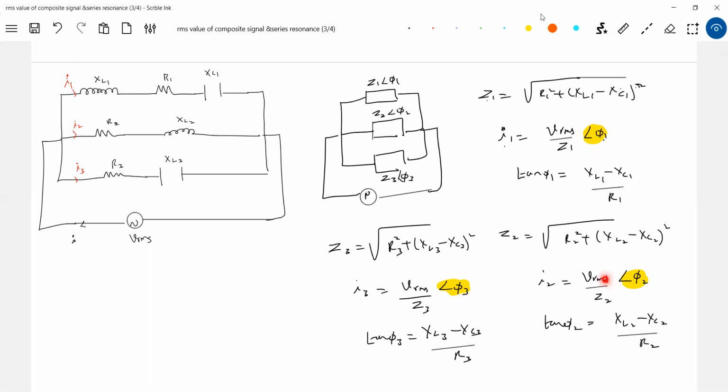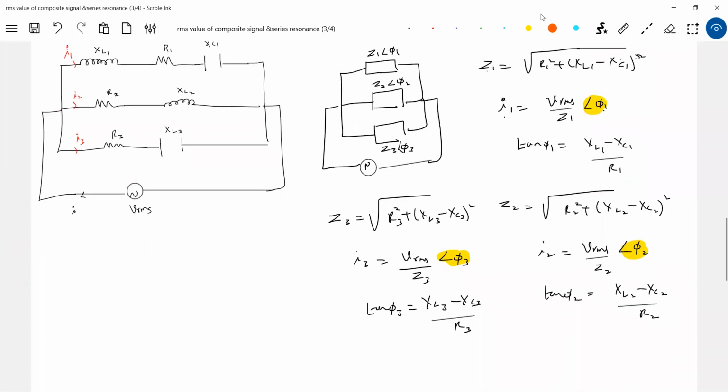How to calculate the resultant current? You can't just add I1, I2, I3. You have to take this angle also. It is as good as you can't just add three forces F1, F2, F3, that is F1 bar plus F2 bar plus F3 bar. Then I should go for the vector sum of these currents. How do you do the vector sum? So if this phase angle is positive, this is this one. So we can resolve all that. And one can be negative.